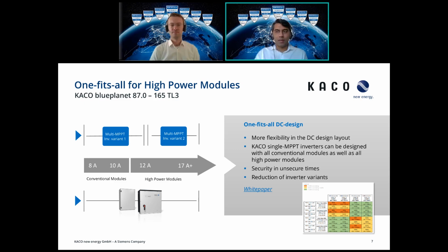But there is seldom an inverter that would be suitable for both low ampere modules and high ampere modules, and that can be seen within a white paper that we have written. We have compared various inverters, multi-MPPT topology with different types of modules available in the market right now, and seen how they fare and how easy it is to do sizing with them.